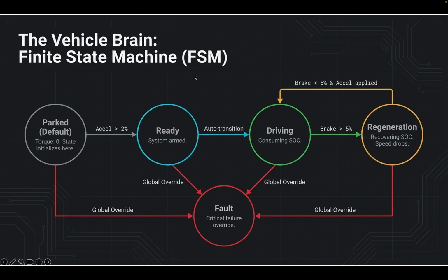And this is the final state machine which I learned from this internship. Here you can see from the park stage, how it goes to ready stage and auto transitions to driving stage. And if something gets overridden, the machine automatically goes to fault stage. And when the driving is on, SOC gets consumed and the charge gets reduced. We even coded all the things manually and know how actually the code works.